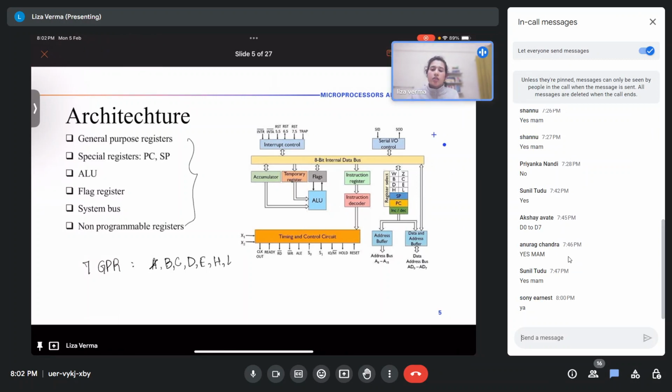Yes, perfect. So program counter, everyone will know it contains the address, but it needs to be understood that it will hold the address of the next instruction, not the current instruction, right? Once the address is used to get the instruction, the program counter is incremented so that it points to the next instruction. And when the microprocessor is ready to implement the next instruction, it doesn't have to wait for the program counter to increment to get to the next address, right?